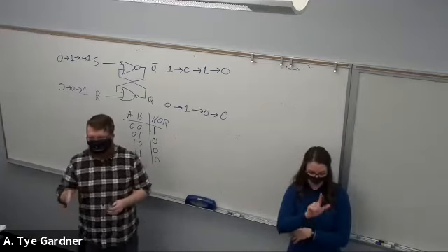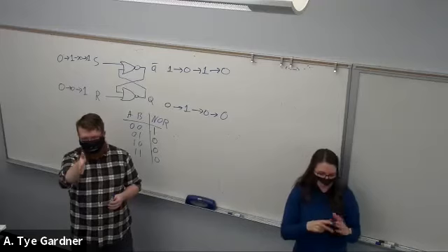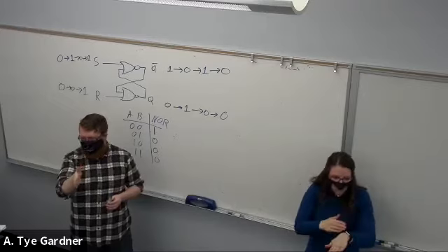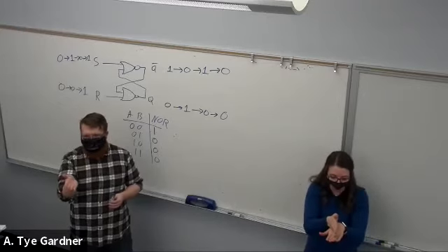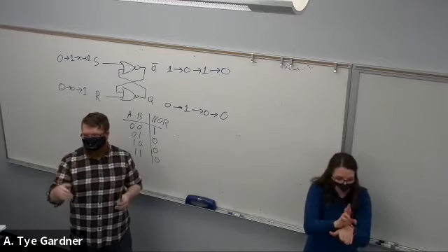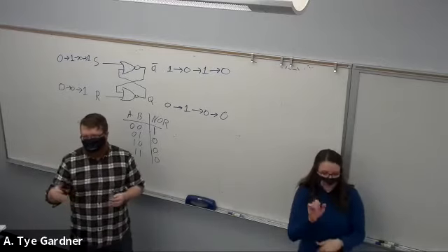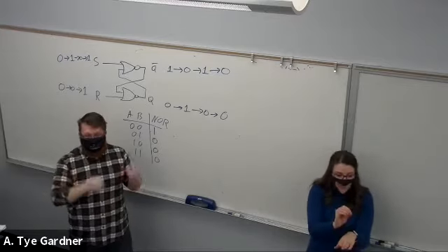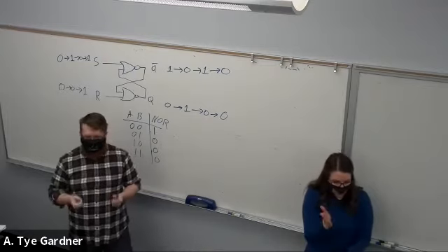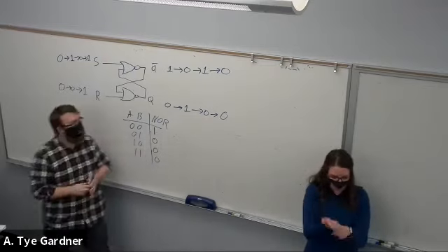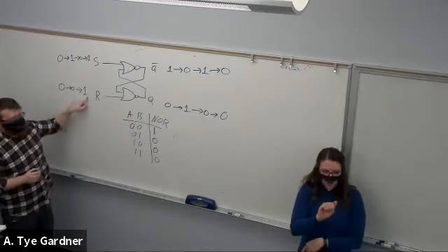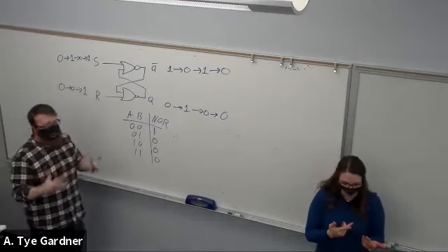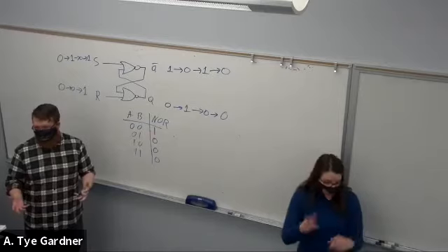And what that means is it's like taking a card and laying it on its edge on a table and trying to keep it balanced there. Now, it's going to end up either a 0 or a 1. It's going to get there. It's just waiting for the random processes, like the air blowing around or other things happening, where the card is going to wobble and fall. So it's going to be a 0 or 1, and we don't know what it is. That's metastable. So the problem with set and reset simultaneously is that we can end up not knowing what the output is. We just don't know.